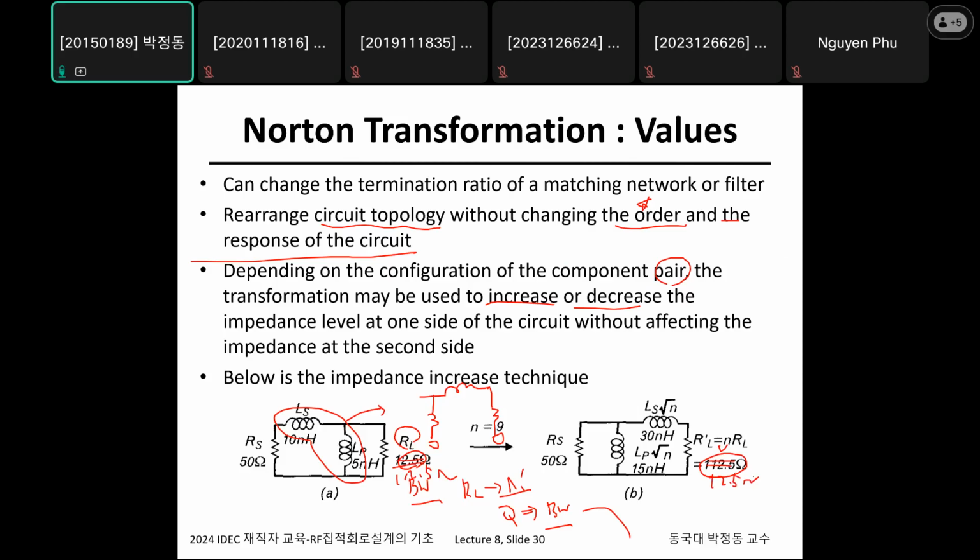We follow the same design concept. So we just swap the direction of the L matching network, because this inductance is larger than this. Definitely, this part must be here. But anyway, let's assume this is correct.